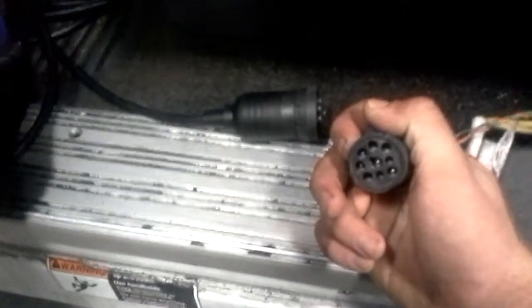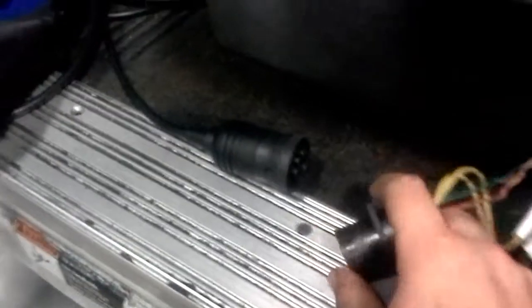Now, how this schematic is set up is kind of like a ladder. On each end of that ladder, where it's closed off, you have the control modules in between. You have your engine control module and you have your ABS control module. Now this isn't the whole truck, this is just a part of the truck. Let's just say you're getting communication between your engine control module and your DTC scanner, but you're not getting your ABS module.